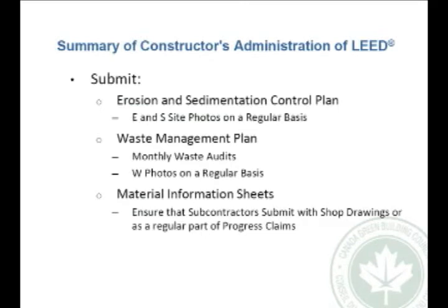There's many things that the contractor is responsible for under LEED. Erosion sediment control plan. They have to submit the photographs of it. It's up to the contractor as to how he's going to do that. It's not up to the design firm to tell him how to do his work, but what the end result is. So a lot is up to the contractor in this regard, but he's got to document and prove that he's meeting the requirements.